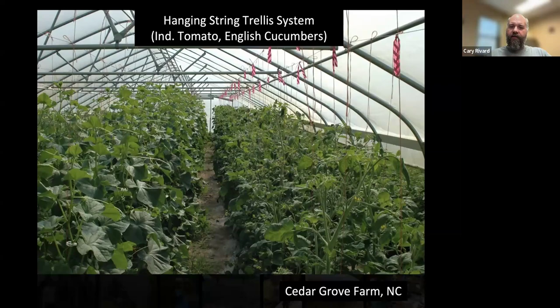So if you're going to do that, keep in mind that you're going to have a lot of vertical load, or a lot of vertical weight, pulling on that tunnel, and it's going to be important to get a tunnel that's strong enough to hold that. The other thing to be aware of is that you're typically going to be attaching these cables to the end walls. So if you're going to be doing that, you want to beef up your end wall, make it stronger so that it can hold that weight. I have seen tunnels collapse from the end walls in, because the weight of those tomatoes just pulled it right in. So you want to be real careful about that as well.